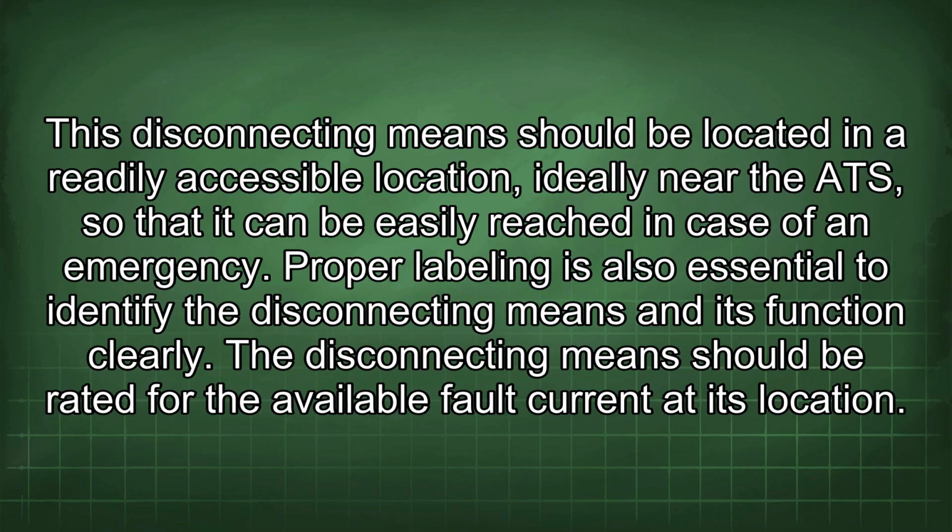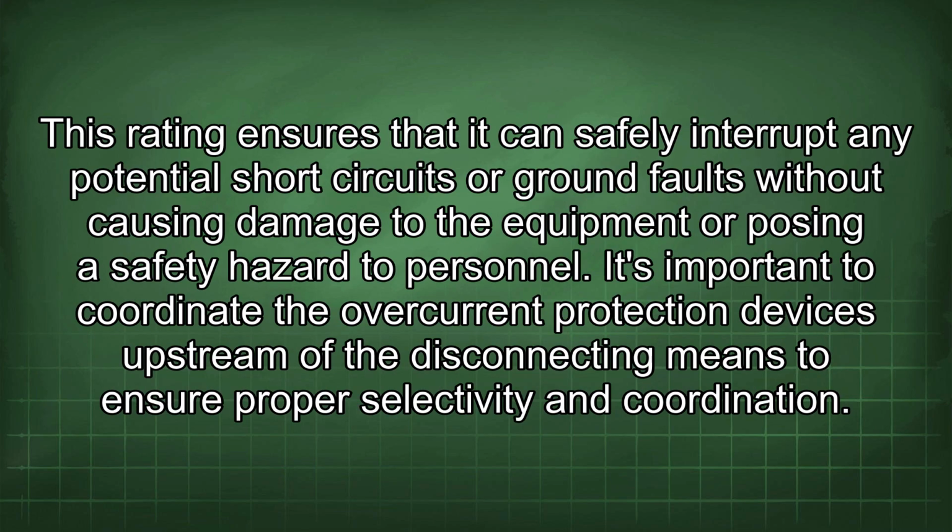The disconnecting means should be rated for the available fault current at its location. This rating ensures that it can safely interrupt any potential short circuits or ground faults without causing damage to the equipment or posing a safety hazard to personnel.